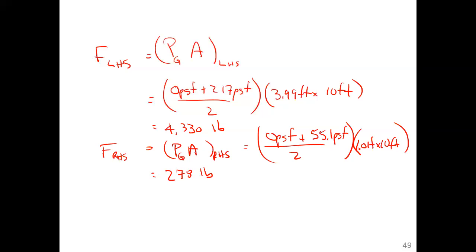All right, since you're so good at this now, let me ask a really foolish question. Where do those forces act? So let's look at the left-hand side. Here's the left-hand side, and here's the pressure distribution. What is the shape of that pressure distribution? Triangle, very good. Where is the center of area of a triangle? One-third up from the base, right?